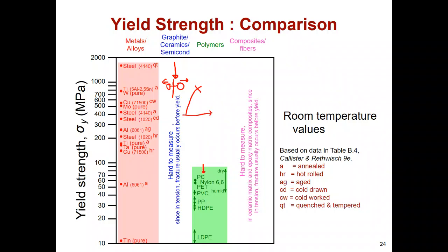But the yield strength is defined after unloading, when there is a 0.2 percent value. The ceramic or similar structures can break immediately, so they cannot sustain their structure up to the 0.2 percent.